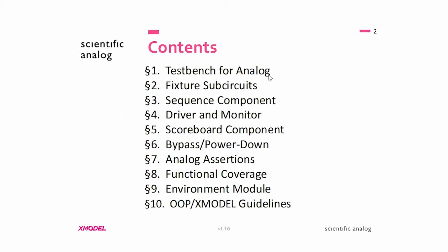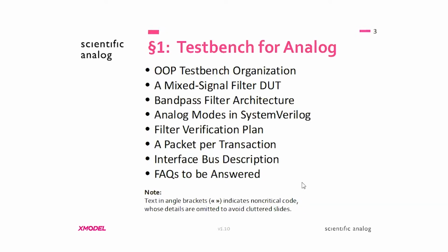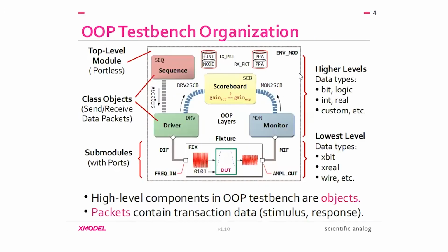We'll start by looking at the test bench organization and the DUT itself. We'll drill down into key components like the scoreboard. We'll even look at writing analog assertions using SystemVerilog syntax. And we'll wrap up with a dozen handy guidelines. Section 1, let's look at the test bench and the DUT itself.